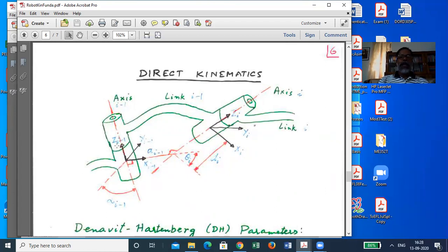Now, to one link you attach another link, to that you attach another link, and like that, from the frame which is fixed to the hand and effector, the sequence of links proceed. That is typically. If an atypical situation arises where there are branch chains, then the same formalism has to be applied again for the branch chain separately from the point of departure. Anyway, so the frame is link 0, then link 1, then link 2, and so on.